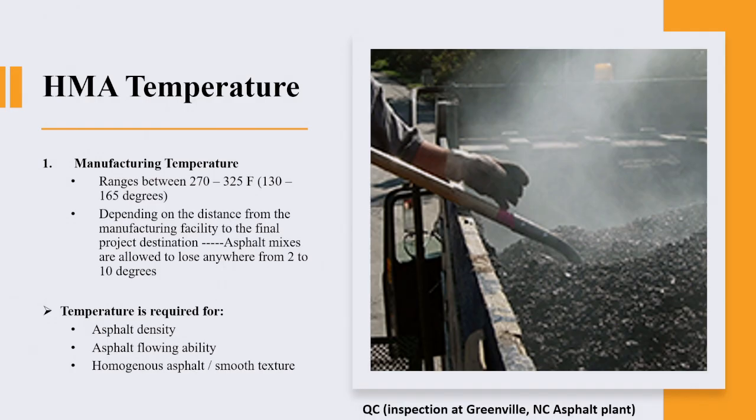So this problem is always there in the highway pavement industry, whether you use RCC, roller compacted concrete, or flexible pavement. Again, there is no stringent rule other than: for RCC, maintain the workability, I mean, don't let it harden or initially set. And for hot mix asphalt, don't let the temperature drop more than 10 degrees.